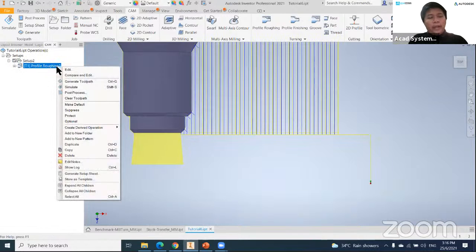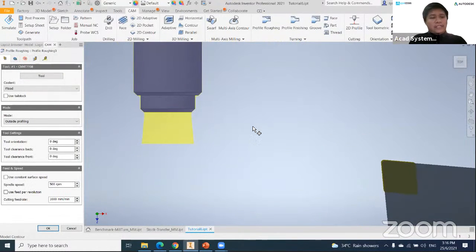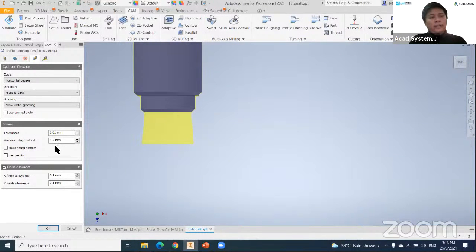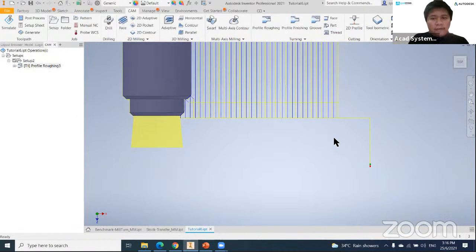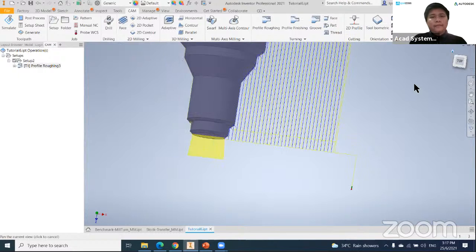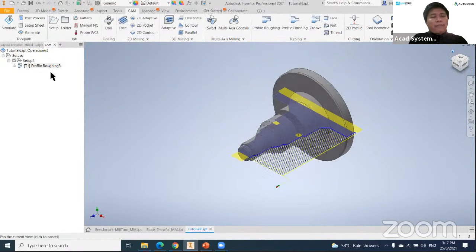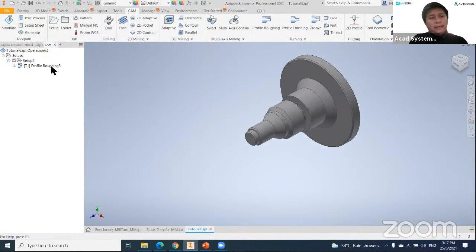This depends on how confident you are in your machine and how experienced you are using this turning machine. I highly recommend you make the value not too big. So in this case, I just want to leave it at 1.5. Then the tool will cut your stock every 1.5 mm.